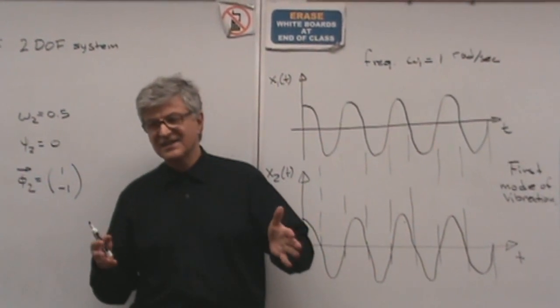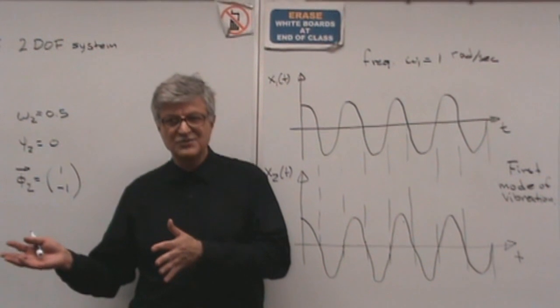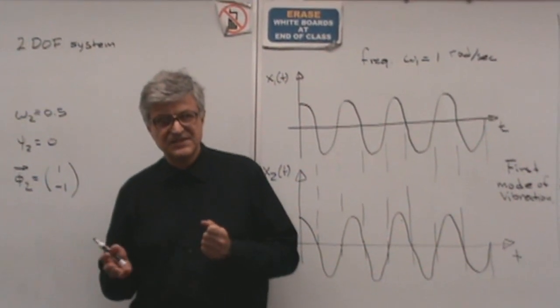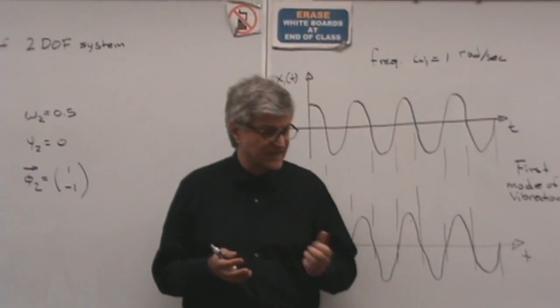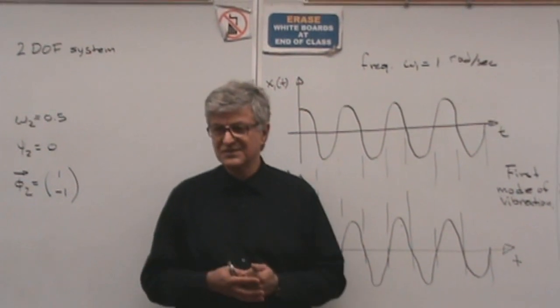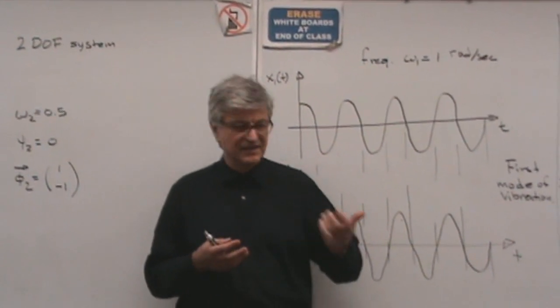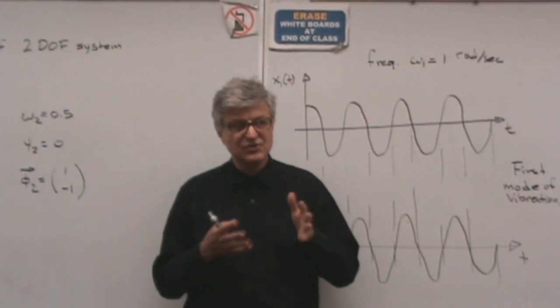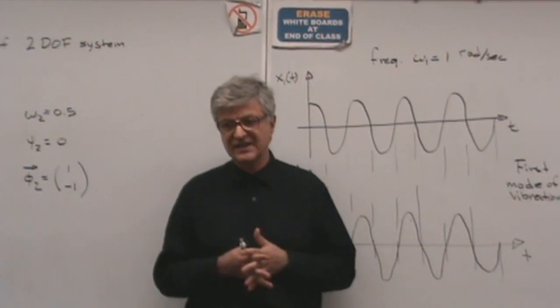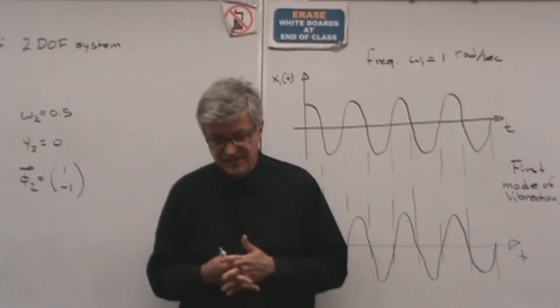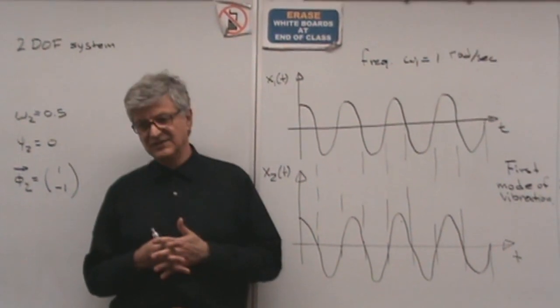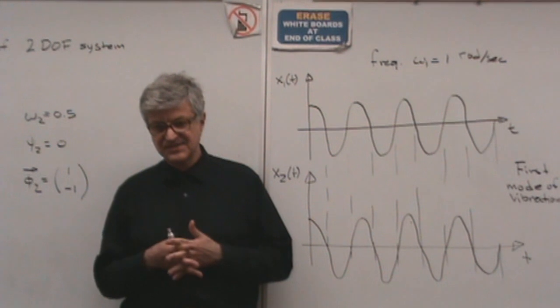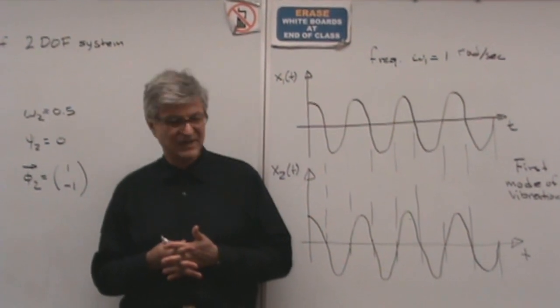The remaining modes are not excited. So the system actually oscillates in the first 10 modes. And using these modes, you can replace this complex system with 1,000,000 degrees of freedom with one that has only 10 degrees of freedom. And that makes our lives much simpler.